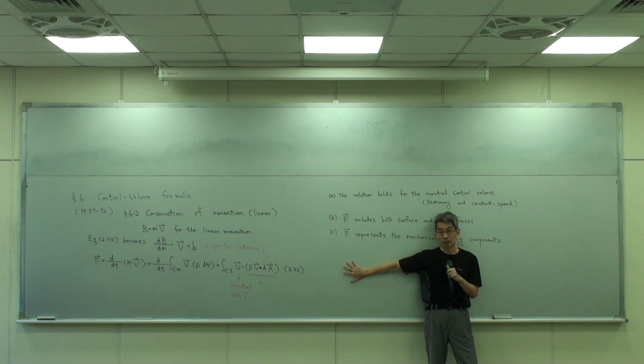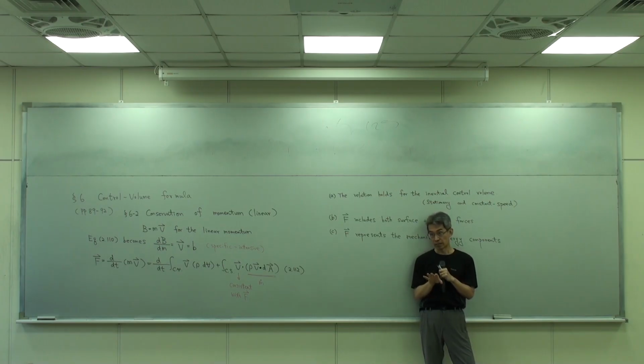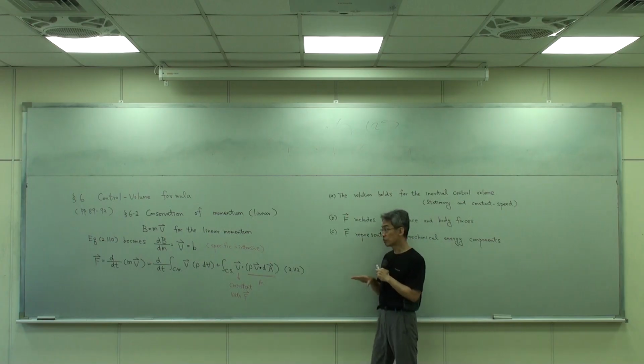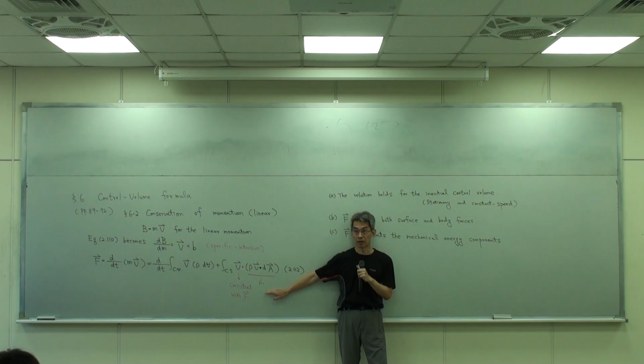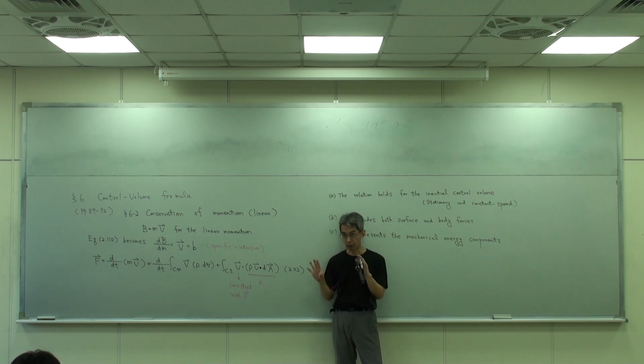Also, you can get the Bernoulli equation from the energy equation, but in the special case of no temperature difference. Because if there is no temperature difference, the components of the momentum equation only include mechanical energy, then those two equations will be the same. Okay?